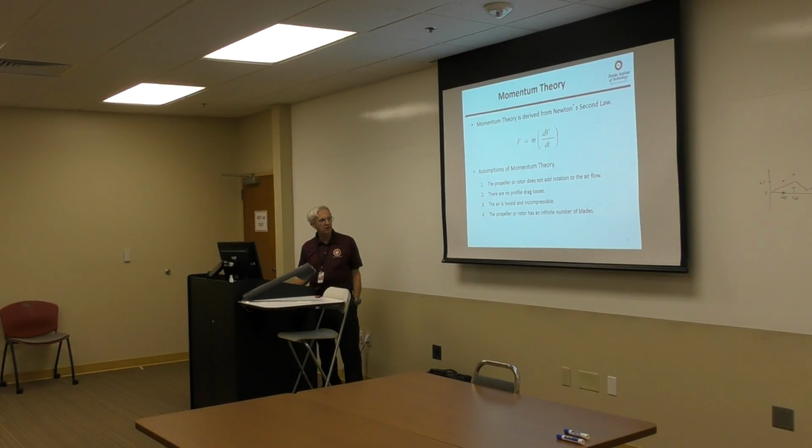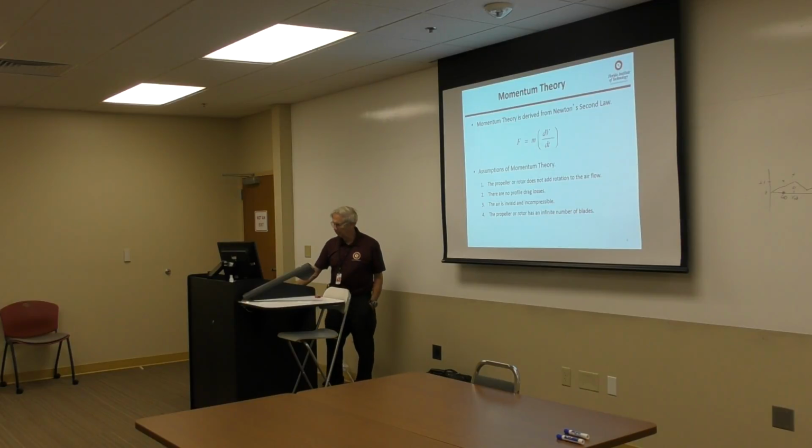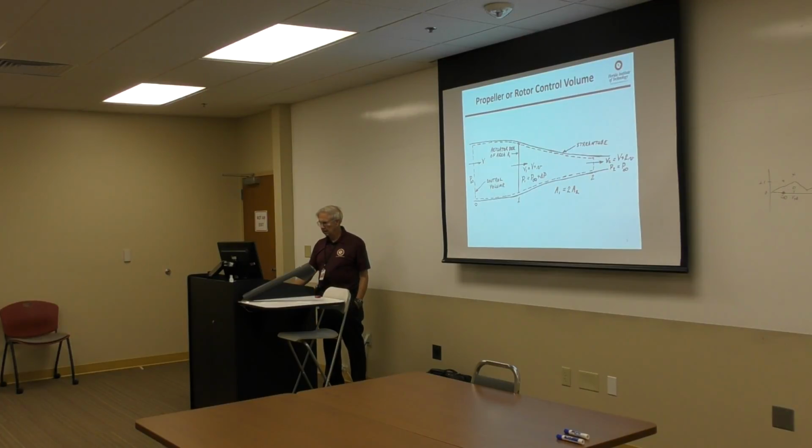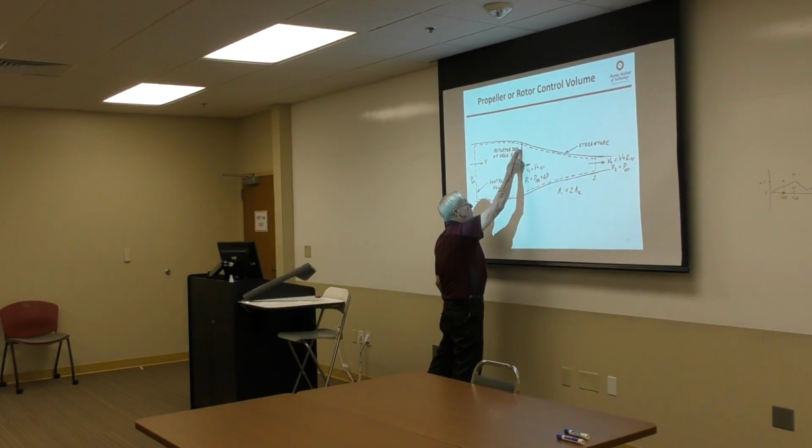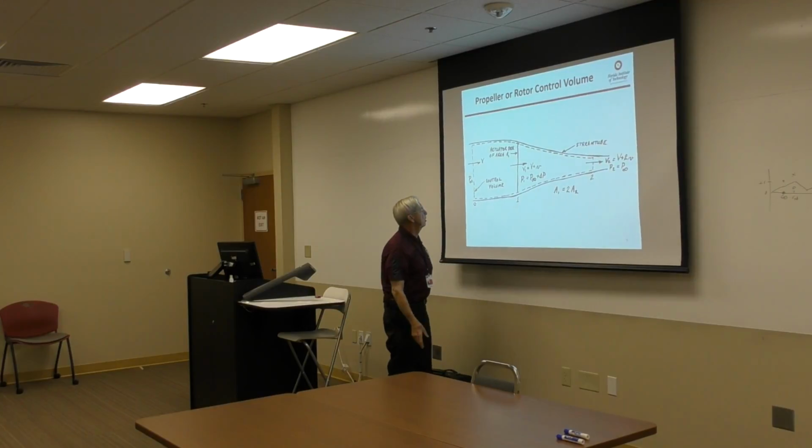There are no propeller drag losses, and the air is inviscid and incompressible. And the propeller or rotor has an infinite number of blades. It's really a disc rather than having blades. And so we can come up with an actuator disc that's here, that would represent our propeller.